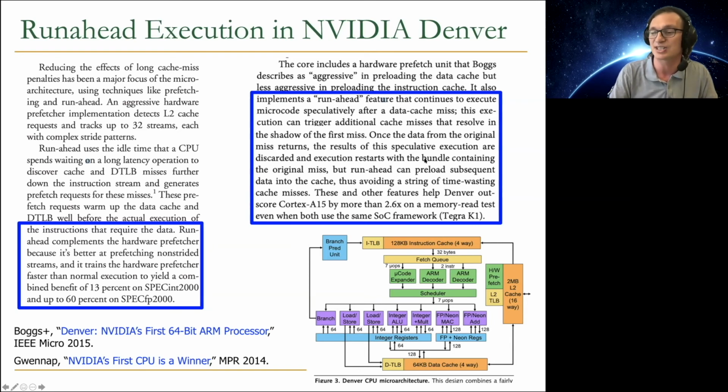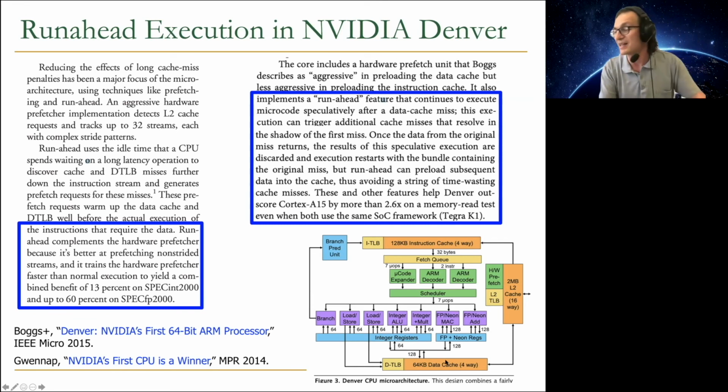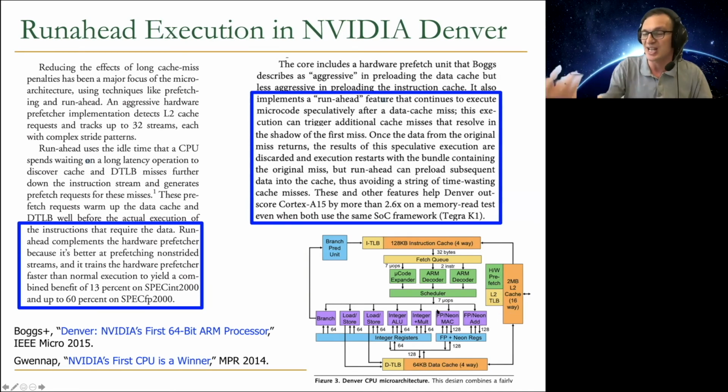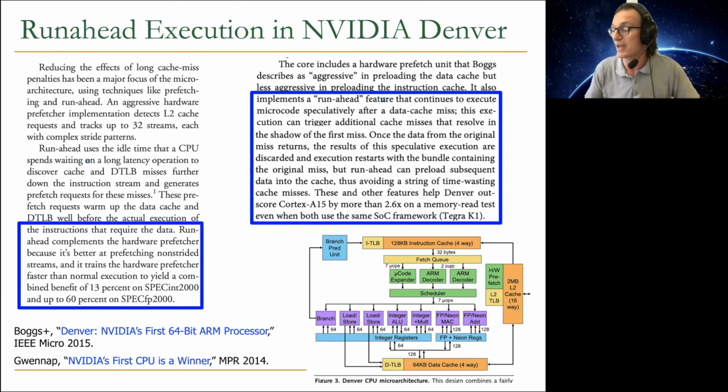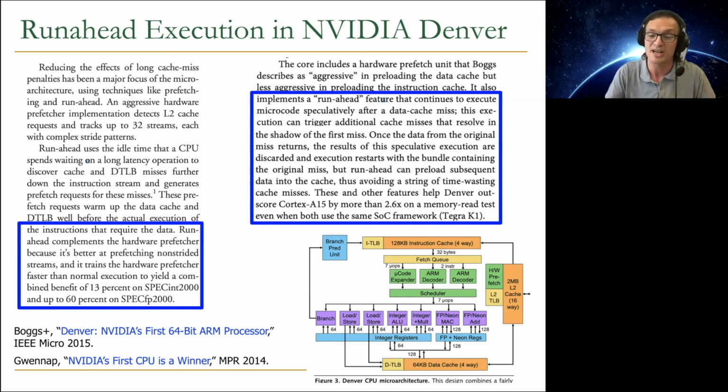So they actually have very interesting features that are described in these two papers. The first paper is more technical. The second paper is a microprocessor report article. And you can read more about how a modern processor does prefetching. You can see that there are already multiple forms of prefetching. And I would recommend reading it because it shows how they do micro-coded binary translation, so they do compilation into a 7-way superscalar processor in a binary translation engine. They take the 64-bit ARM code and translate it into a 7-way internal superscalar micro-operation format. And if you're interested, you can take a look for more.